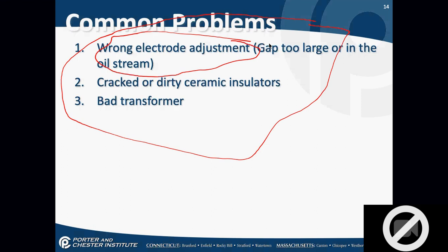Okay, what about the old idea that when you get up to an oil furnace that's having a problem, one of the first things you should do is pull that nozzle assembly and check the electrode setting just manually? I guess you could do that. It would be time consuming, but... Not that time consuming. You can pull that nozzle assembly in 5 minutes. Is it worth the 5 minutes to be sure? Yeah. You're already on site. It's worth the 5 minutes to say, you know what, let's just check and make sure the technician who was here last actually did it right.